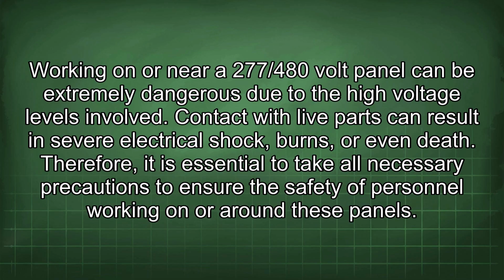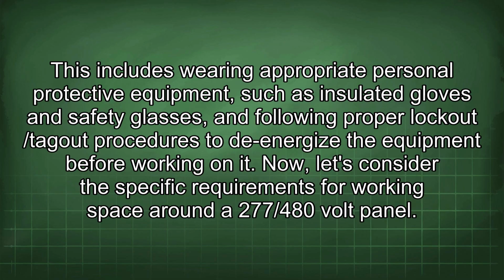Contact with live parts can result in severe electrical shock, burns, or even death. Therefore, it is essential to take all necessary precautions to ensure the safety of personnel working on or around these panels. This includes wearing appropriate personal protective equipment, such as insulated gloves and safety glasses, and following proper lockout/tagout procedures to de-energize the equipment before working on it.